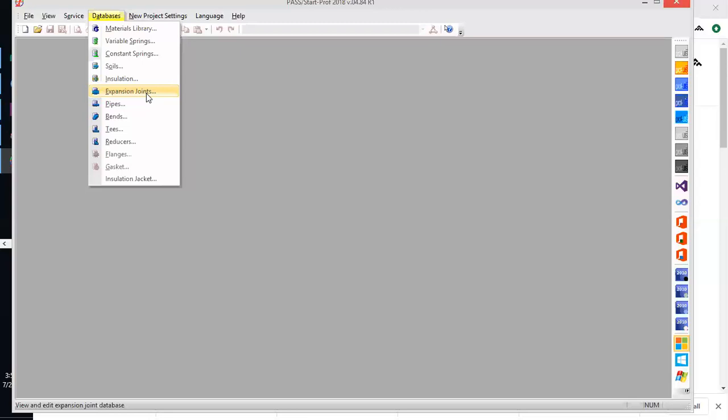Those are gaps that on a very hot day, the metals of the bridge can expand into, and on another day, they can contract backward. So that is the essence of an expansion joint.